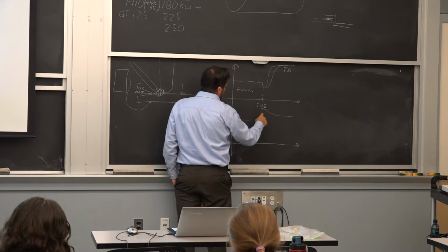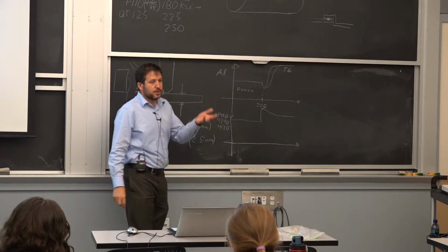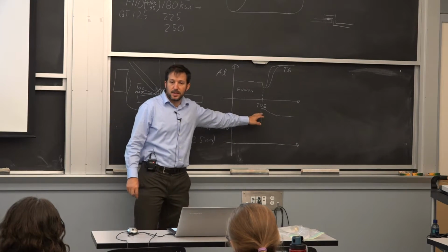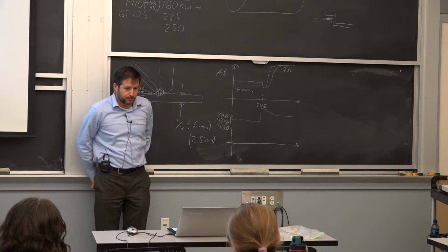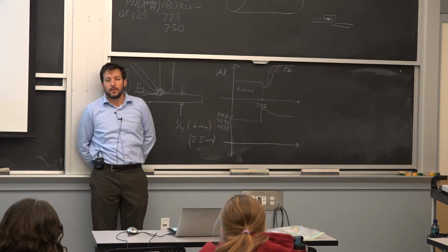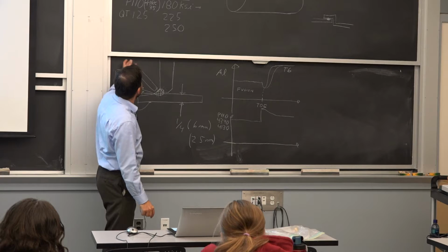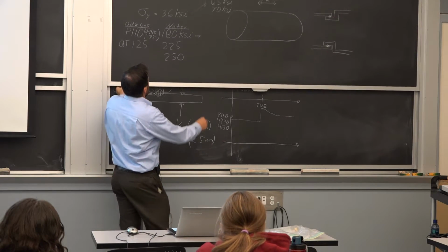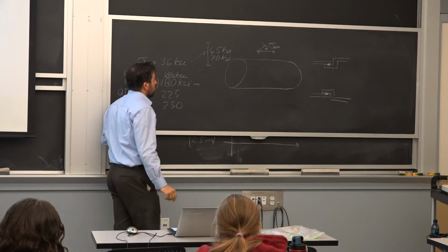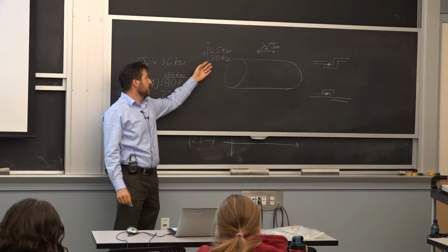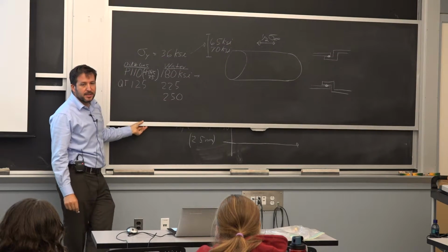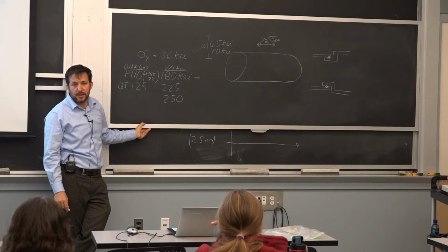So over here, you got it close to the melting point and you cool it down really fast. So that's your Martensite here. And it's a problem in terms of ductility. So when I said that for a welding application, you stay typically in this range, is because the way these alloys are built is not by adding element that makes it easier to get into Martensite zone.